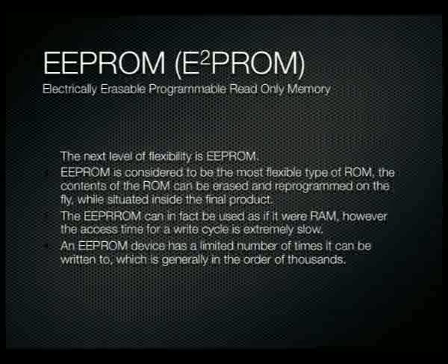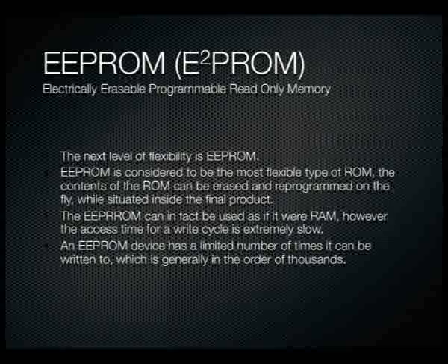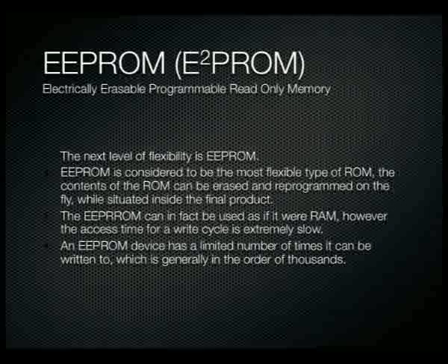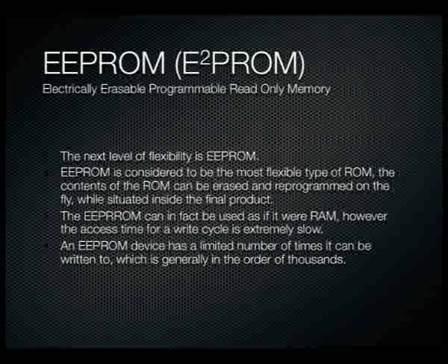After that, the EEPROM transistors no longer work. The floating gate will no longer be programmed. So you have a limited number of write cycles in which you can erase and rewrite EEPROMs. So there is a downside to using them.